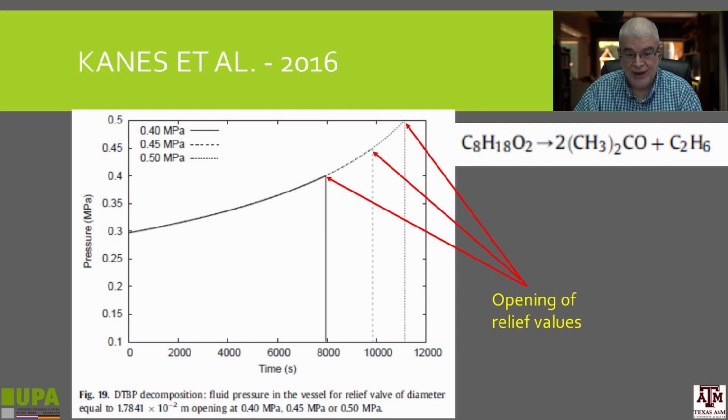If you have a valve of the correct size, then you kill the reaction, because you discharge the reactor completely. Now, if the relief is not designed properly, you may have a situation where the pressure decreases, then increases again. So that's why it's important to get it right.